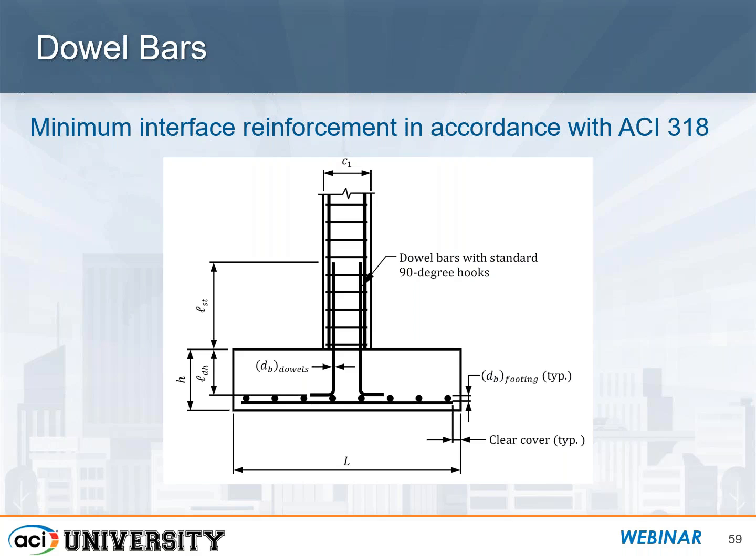There's not much going on up there with respect to seismic forces. They're much smaller than what's going on in the first floor. So providing just a typical detail for constructability, my best guess would be it should be fine. I can't think of anything. You're going to have a beam there. As long as you develop everything into the beam, it should be fine.